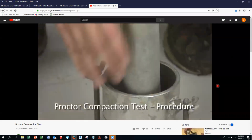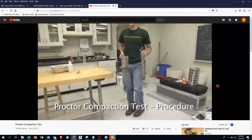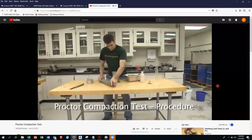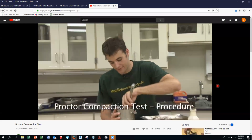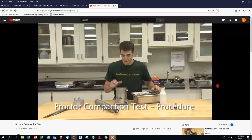It's got like a rhythm to it. After 25 blows, take the mold back to the table, scarify the surface, and add more soil for the next lift. Scarify the surface of the first compacted layer with a spoon. This will ensure that the second layer will bind to the first layer well.